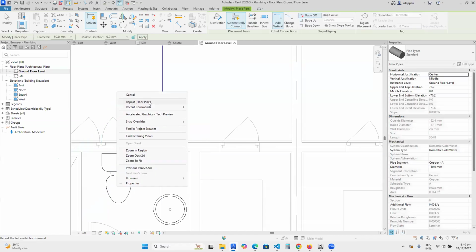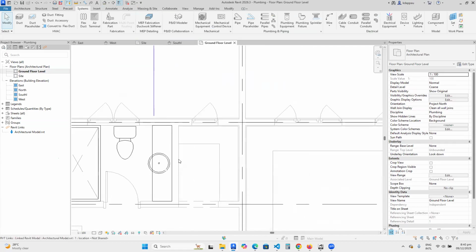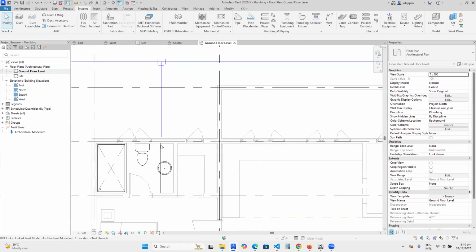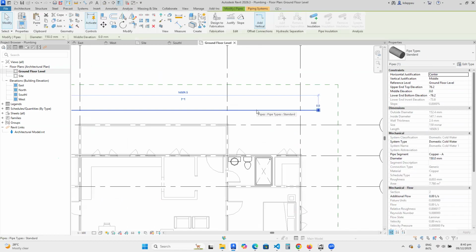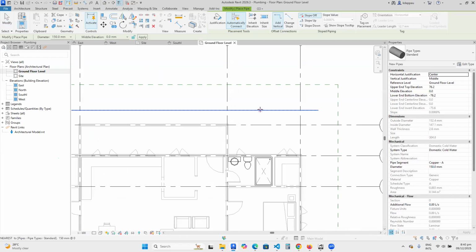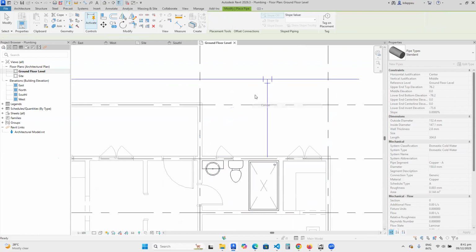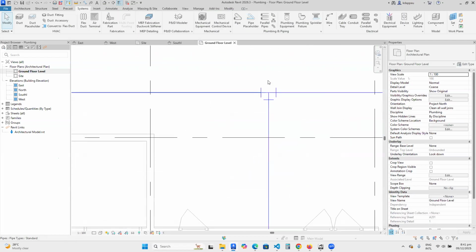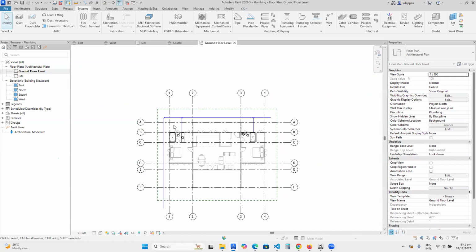And when I reach it here, I can always route it to the left and bring it to the sink. I can route it to the right and bring it to the WC. I can pass it all the way here, bring it here, and then add it to the shower, depending upon where I want to place my shower. I can come in here also, create similar, and then connect it from here to come and join, say, there. When you add them, Revit adds the fittings for you. It adds a fitting here, it adds a fitting here.